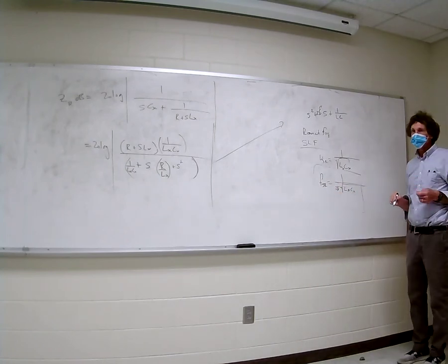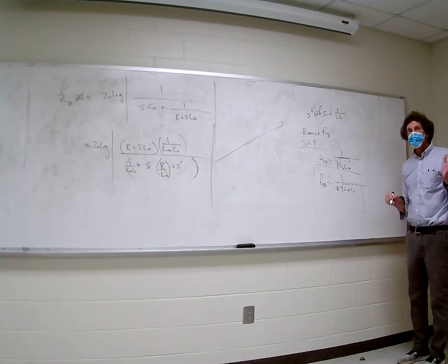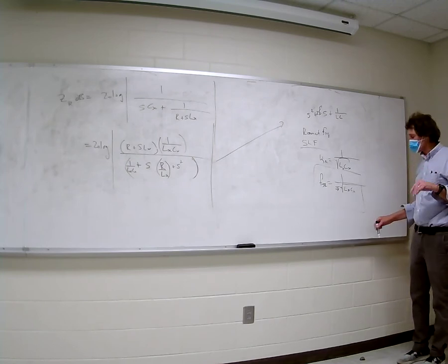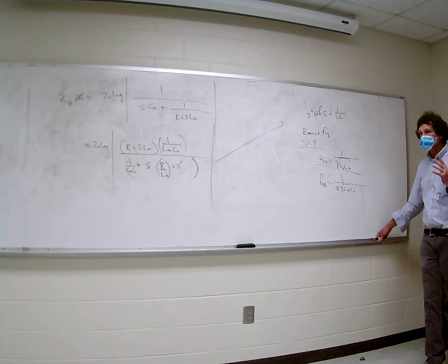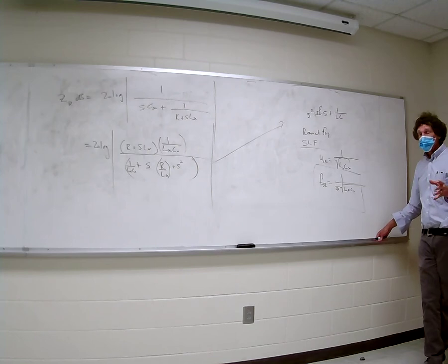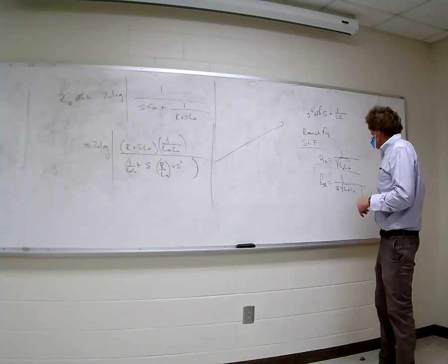That's the self-resonant frequency. If you build anything and you've got a known self-resonant frequency, you don't ever want to operate that resistor at more than 50% of the self-resonance value. For instance, if it's 10 megahertz, you don't want that resistor in a circuit where you're operating at 5 megahertz frequency components, or else you're going to have problems. It will no longer act as a resistor. Do y'all follow me in this class? So you have to understand self-resonance for operations.